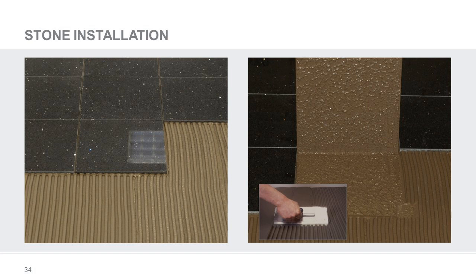However, when tiling to external locations in wet areas such as showers and swimming pools, solid bed fixing of 100% should always be the installer's goal. It's advisable to lift the tile now and again and check solid bed fixing is achieved. Ensure that the mortar has been applied in ribs and the back of the tile buttered with a thin layer of mortar before it's firmly pressed in place with a sliding action back and forth within the open time of the mortar prior to a skin forming. This method of installation allows for full contact of the mortar with the back of the tile and the substrate.